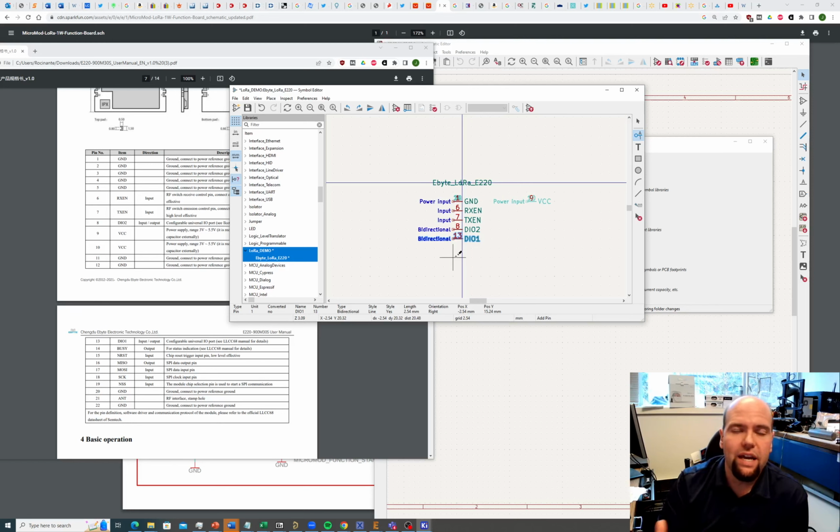It's sometimes better to wait until you're in the PCB, when you're actually building the PCB, to check this stuff. Because when you're actually checking the PCB, you should have a pin name so you can look at what you labeled that pin, what you labeled that signal. You can look through the data sheet for the part, look at what's actually on the PCB, and just triple check that it's right, because you're totally in control here. Any mistake you make is not going to get caught.